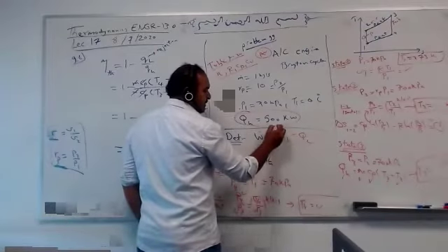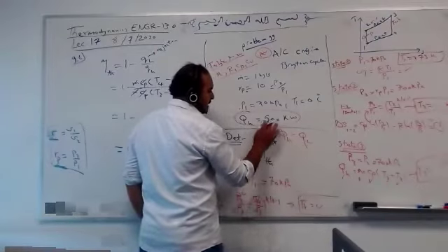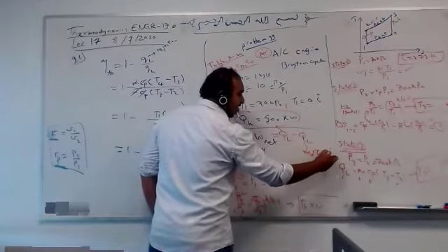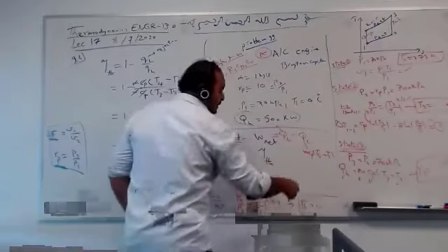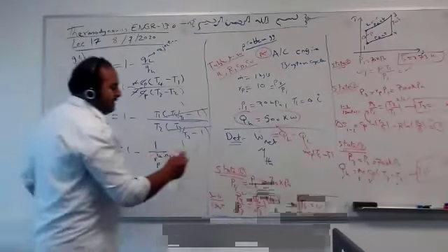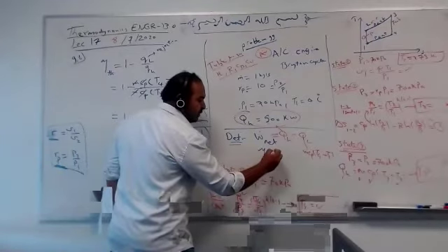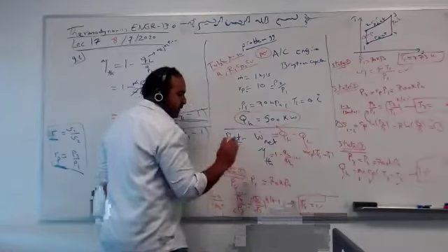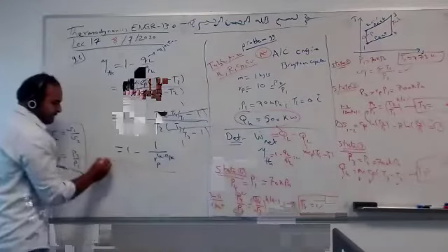This one is given, and this one, because it's kilowatt, is m dot Cp, T4 I have minus T1. So the whole thing is to get T4. If you want to get the thermal efficiency, that's actually required, but we can do it like 1 minus Q low over Q high. And you get it. You know what? It's also equal to that.